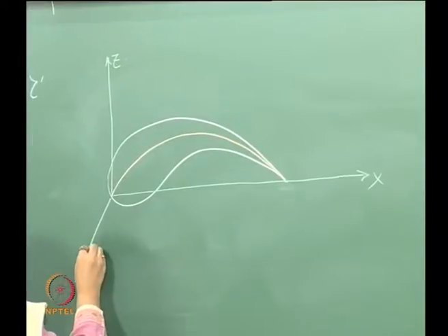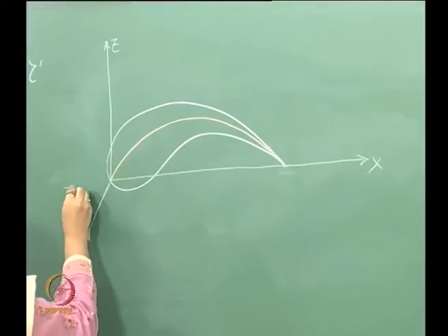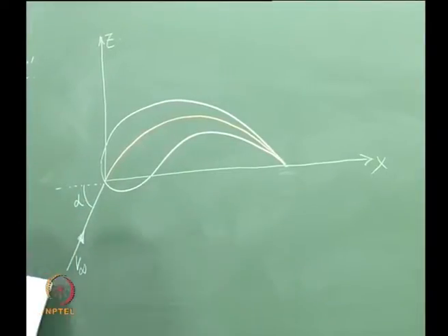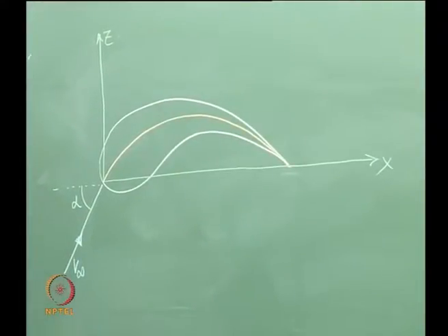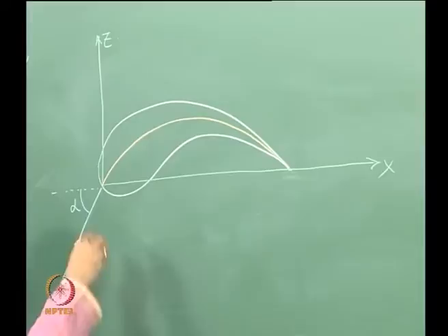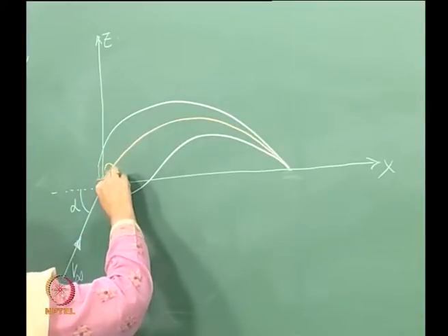You can have a free stream making an angle of attack. Now, numerically, in order to calculate lift, we basically have a vorticity distribution over this airfoil. So, the way we will go about that is let us say we have a distribution of vortices which looks like this.